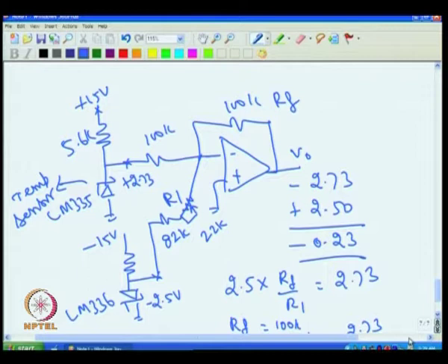So, you can adjust this potentiometer, say I will call this as P1, and of course, this resistance is R1 here. So, you have this resistance we call R1 82 K, and this is P1. So, adjusting P1, we can calibrate this instrument, that is keep this one at ice and adjust P1 to get 0 volt at this point, that represents 0 degree C.